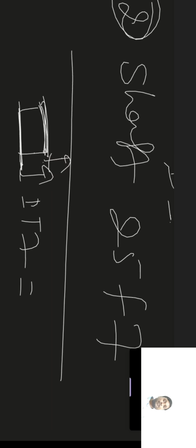Only 25 represents only the basic size, and 7 represents only IT7, that is the grade of international tolerance grade. I means international, T means tolerance, IT international tolerance grade. So to represent a hole or a shaft, we have to specify the basic size, the fundamental deviation, and the standard tolerance grade. Alright.